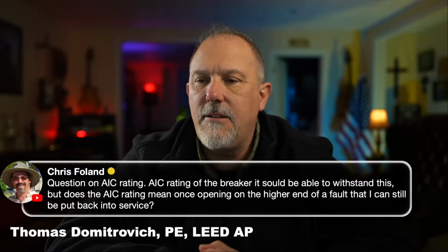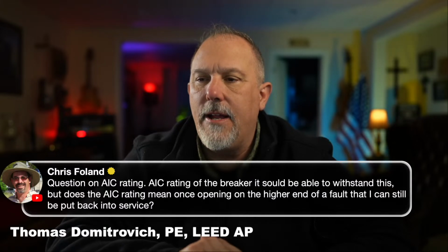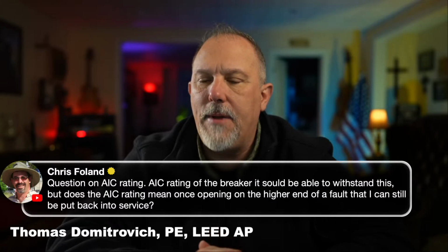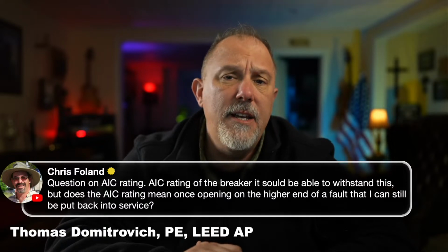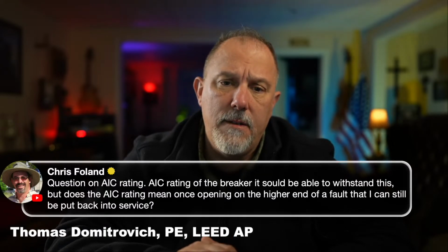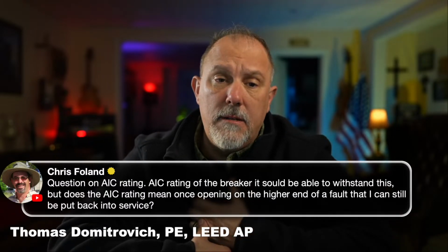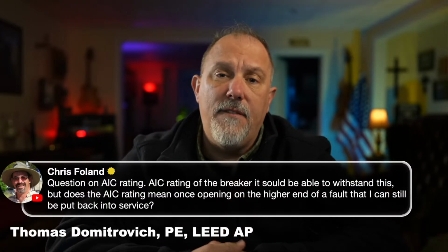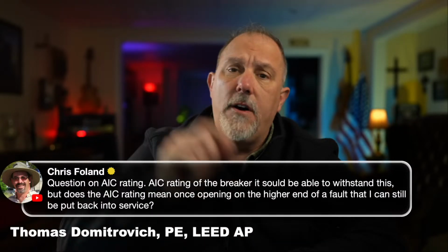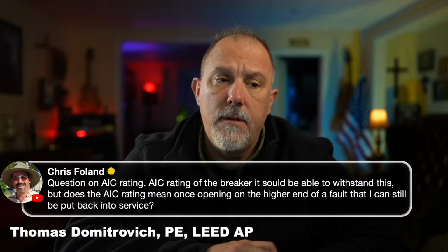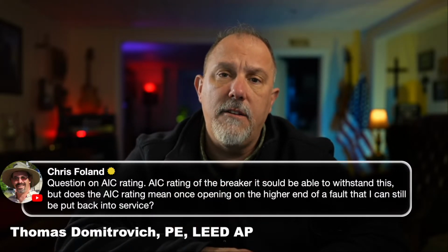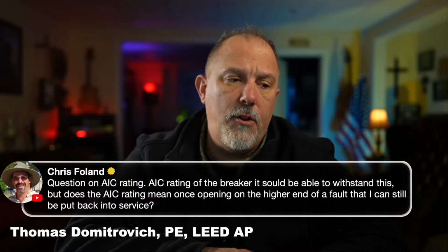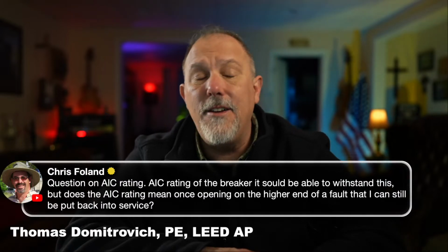But does the AIC rating mean, once opening on the higher end of the fault, that I can still be put back into service? Chris, my suggestion, this is Tom speaking: if I know I had a very high fault current, I would take that breaker out, follow NEMA AB4, and put it through the wringer just to make sure of that device. You may see information that says, well, you could take one hit.